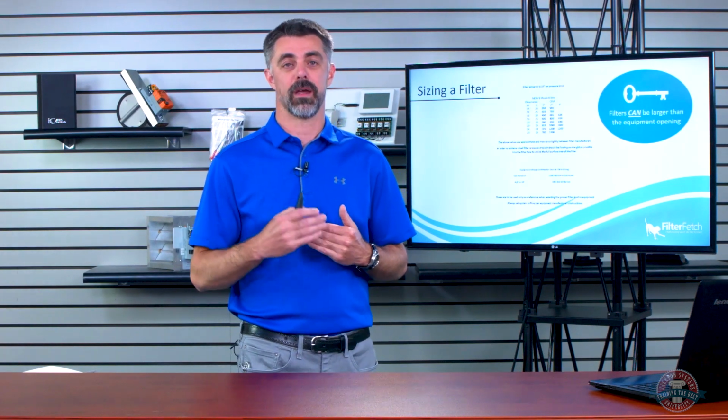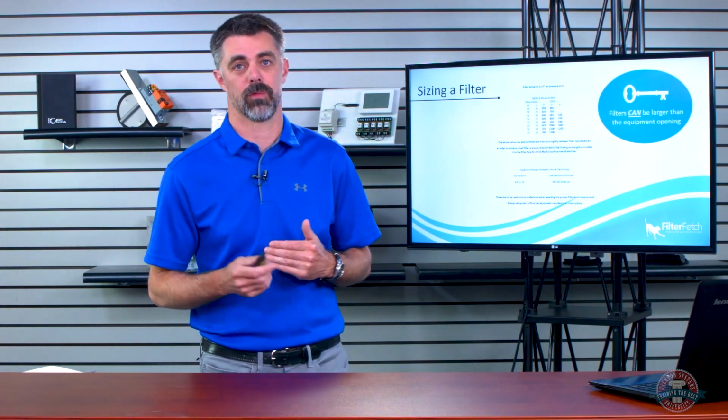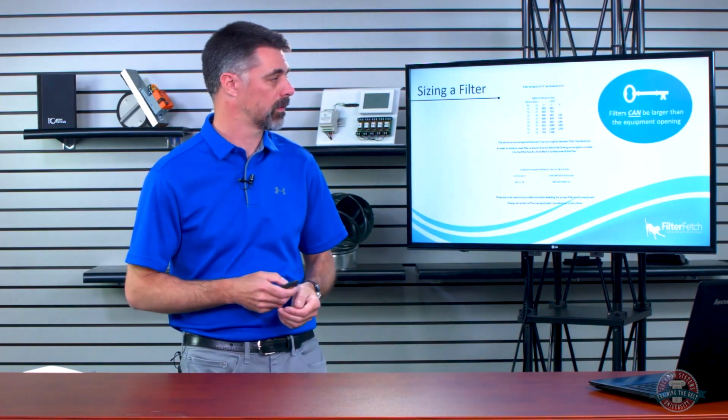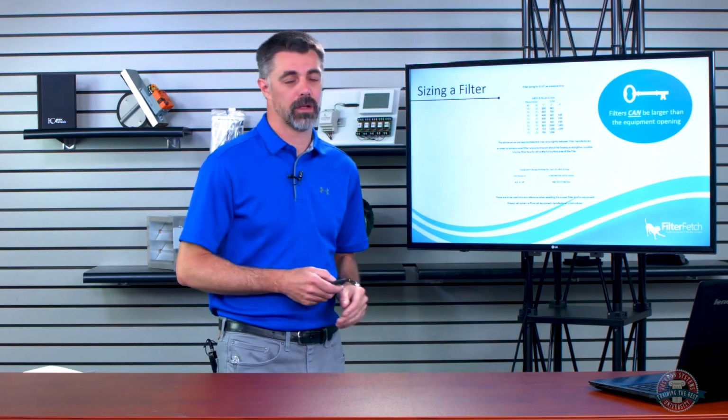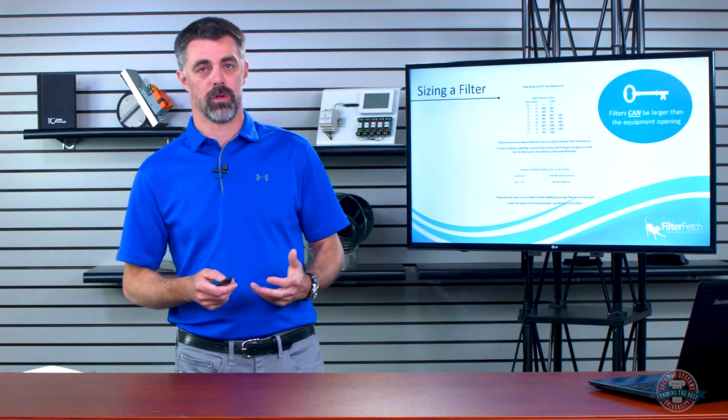I've been asking several filter manufacturers for pressure drops or for rated CFM at that 0.1 pressure drop, because that's typically where we need to design in the residential and light commercial world when we're talking about split systems and an external filter rack. All right. So we covered that. It's a handy little chart to have around when you're designing. And again, it's generic. Always go by the manufacturer's filter charts or pressure drop charts first. But if you can't find them, jump to this, and it'll get you real close.